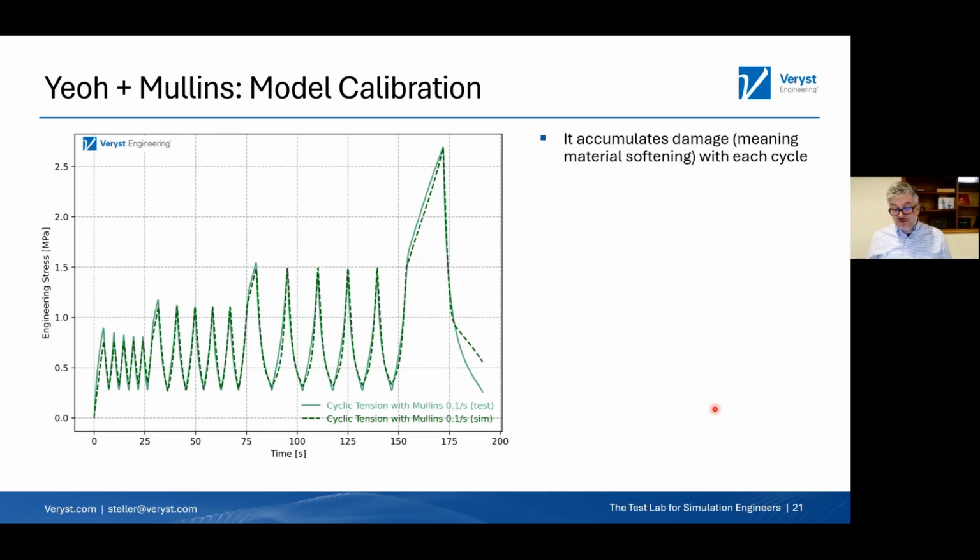Now, you won't want to use something like a Mooney-Rivlin model for that, because the Mooney-Rivlin model can get you in trouble if you don't have the test data necessary to support it. So you want to be careful in your selection of the hyperelastic model you use, but you can. The caveat there is when we're talking about thermoplastics and some of these plasticity models, I would recommend more than one mode, because more than one mode can be important to capture a difference in yield in tension versus compression versus shear, and you need multiple modes for that.